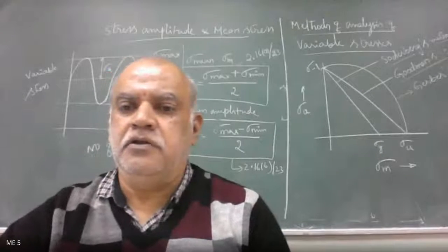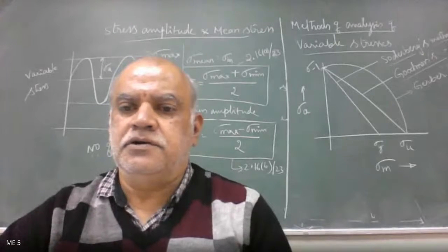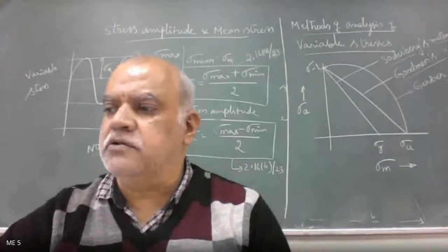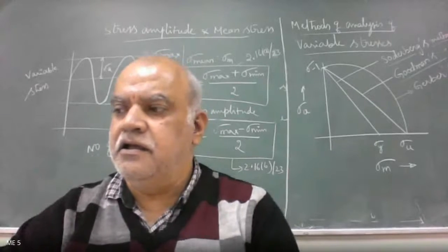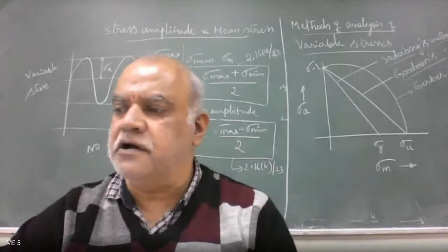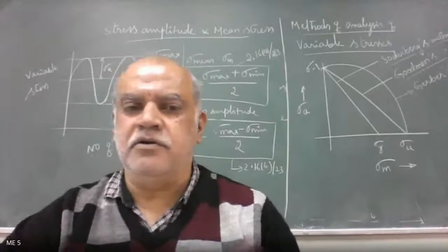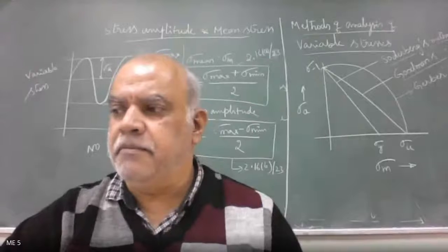Nadella, are you there? Yes, sir. Please read out what is low cycle fatigue and high cycle fatigue. Fatigue failure from N equals 1 to N equals 1000 cycles is classified as low cycle fatigue. And high cycle fatigue is considered with failures corresponding to stress cycles greater than 10 to the power 3 cycles. So what do you understand by this, Ashutosh? Briefly, you can tell me.